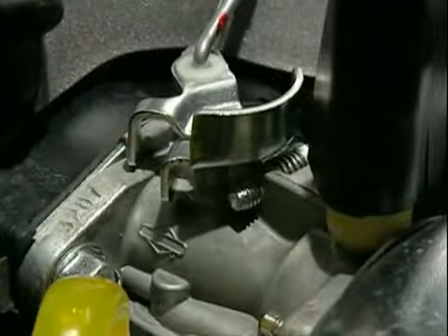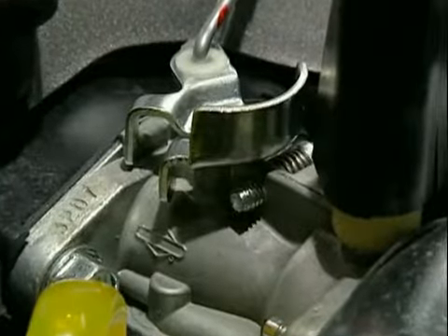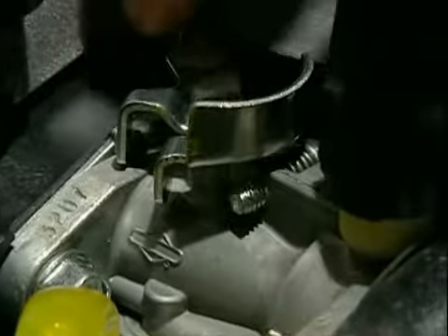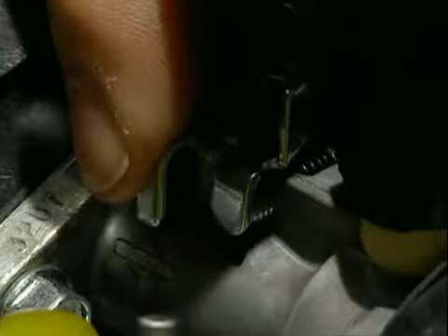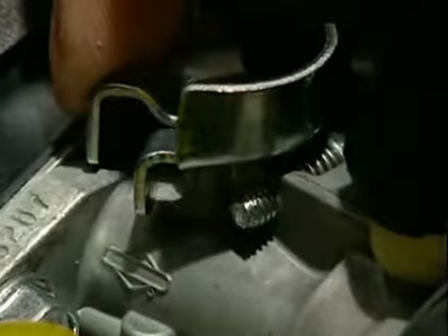You should note that some carburetors do not have idle stop screws, and some carburetors with idle stop screws do not have enough screw travel to allow the speed to be raised to 2800 RPM. Some other method will need to be devised to hold the throttle shaft steady.